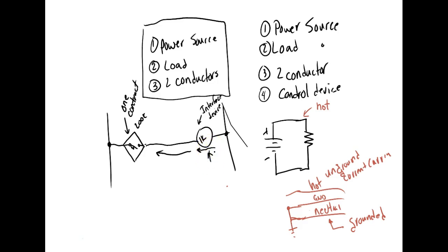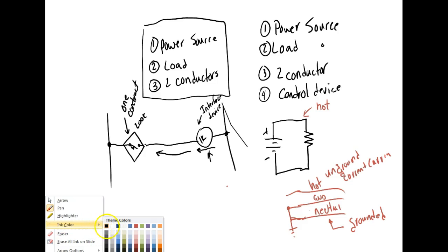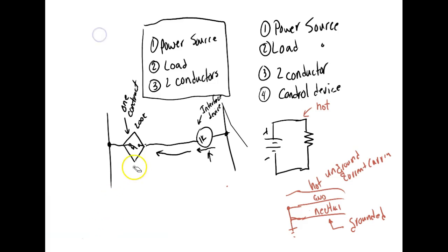Okay, y'all understand that? Some require too much current, like our photoelectric sensor and our temperature sensors. So what do we have to do there? Yeah, we have to put in a power lead. This is still the minimum requirements of a circuit, right? Because here we still have, it considers this to be the load for that circuit. And the main current load that runs our intended control load, which is this one right here, still goes through the solid state relay.